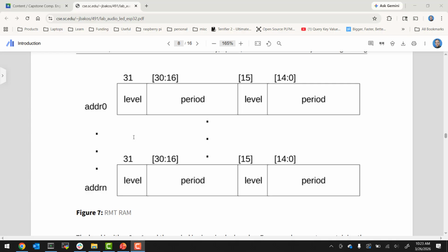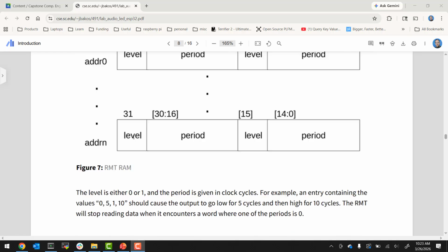So once you send the color out, there's no other control bits, there's no handshaking bits, nothing. You're literally just sending 24 bits, 24 bits, 24 bits. You're sending a sequence of 24-bit values across, which will set up each LED in order of their connection, right? So in the case of 100 LEDs, if you want to do the 99th one, it's the 99th 24-bit value that will go to that guy. That assumes you don't have that reset period, that 50 microsecond downtime, which puts them all in programming mode again, okay? So they're all programmed in order. Make sure you zero terminate that though.